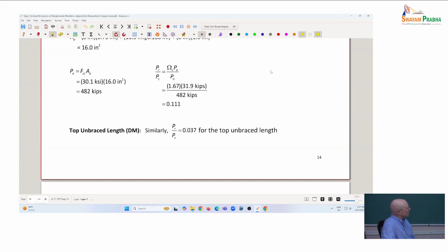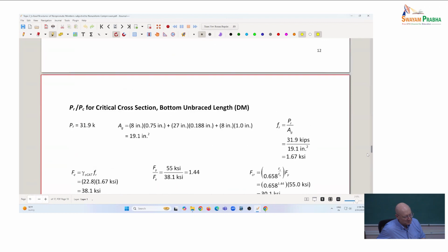In this case, it was a crane loading, I believe, with snow but no wind. So we'd say, okay, we would put on a notional load or an out-of-plumbness in the frame from that. And we're doing all that because we want to get a good estimate of the true forces in the frame at strength. But the more traditional approach is the effective length method, and that would be more true to using the current Indian standard as well.